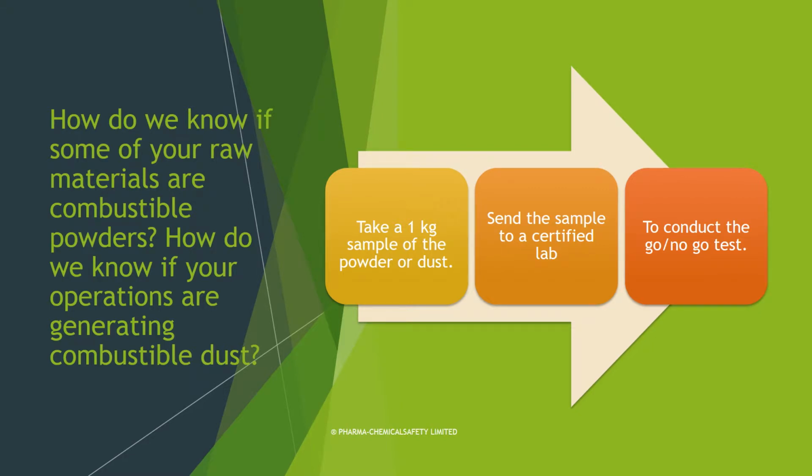So in the video today, we're gonna see different parameters of the combustible powders, what we need to measure or what data we need to get in order to have a better design of our process that involves combustible powders. How we're gonna design and build explosion venting proofs, for example. How we're gonna design our process in case we need to empty super sacks or sacks of combustible powder into a mixer tank, for example. What are those parameters that are important?